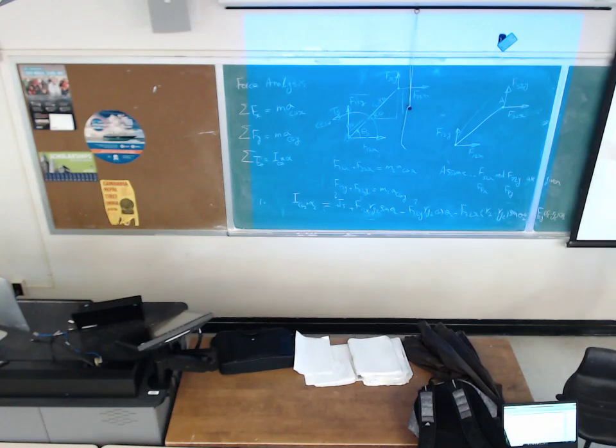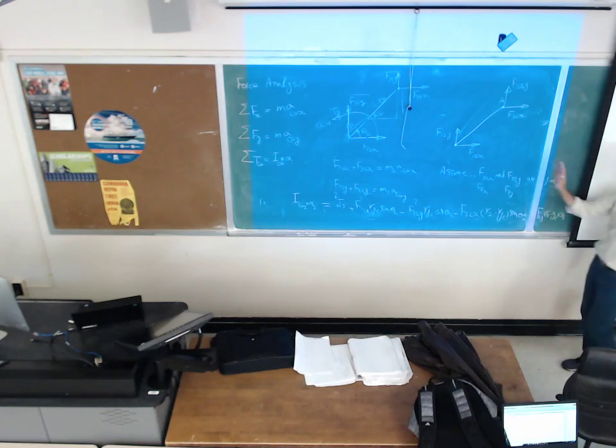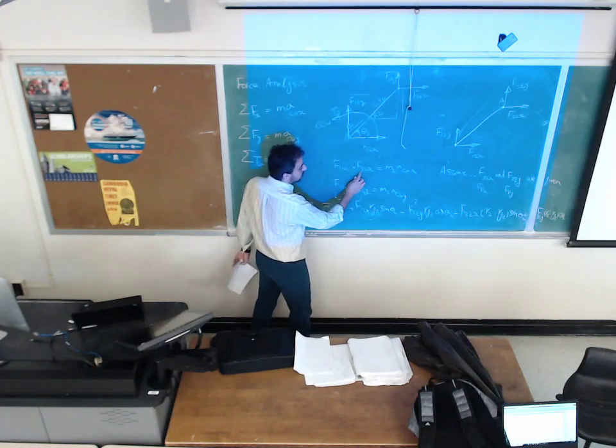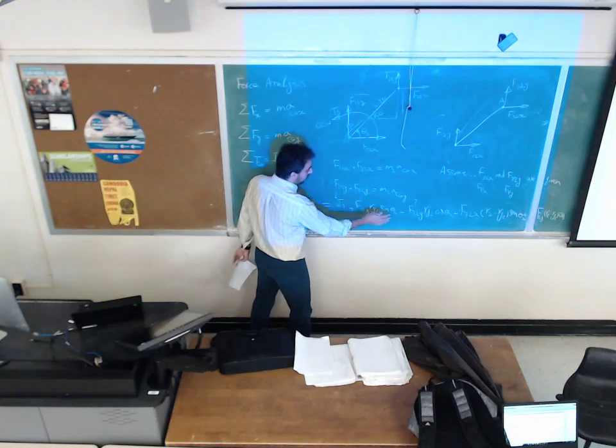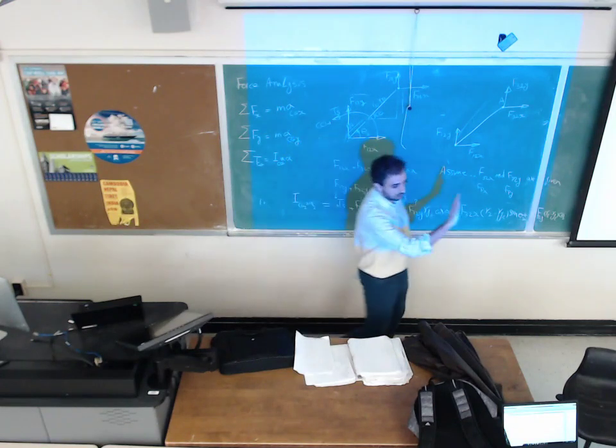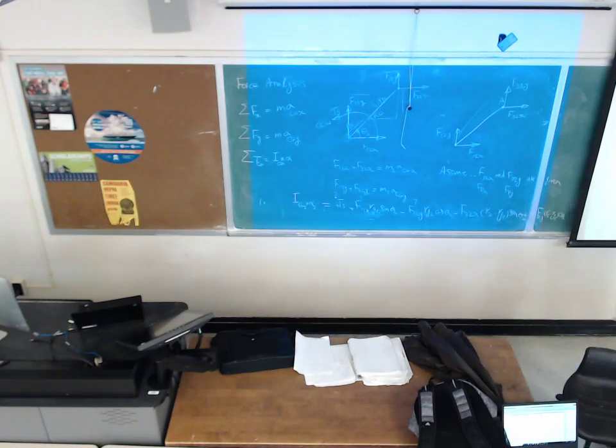Then I'm gonna extend it to the 4-bar mechanism. On 4-bar mechanism, we don't know F32x, we don't know F32y, we don't know F12x, and we don't know Ts. We are solving for all of those unknowns. Not input force, not input torque, none of them are known. Here, since with 3 equations I can solve for 3 unknowns, I'm assuming these 3 are given, just to show you how you can set up the equation.